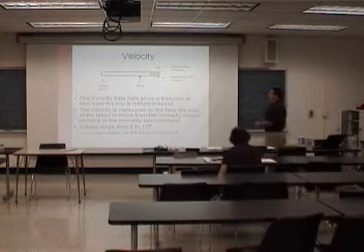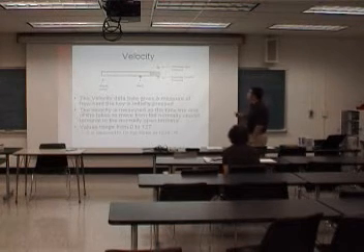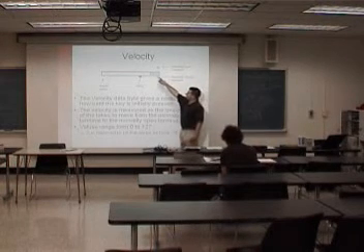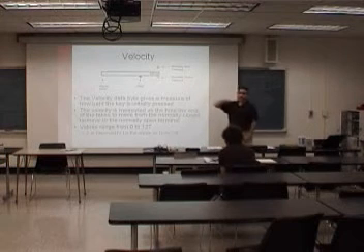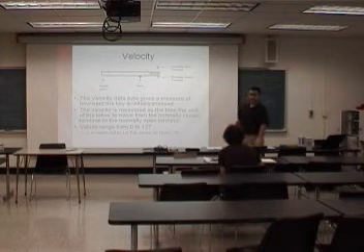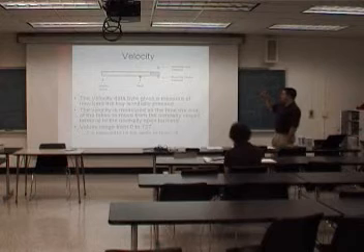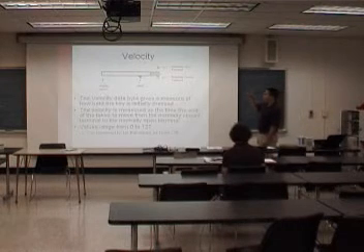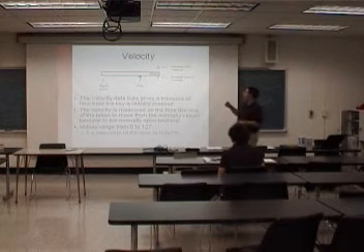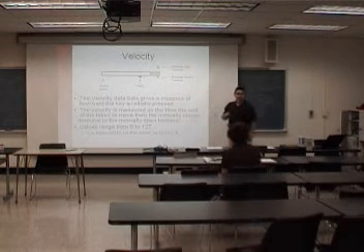Velocity is exactly like you said. It's basically when you push down on the key, you think about having two switch terminals. One that's normally closed, that's in contact with the back side of the key when the key is not pressed, and then one that is normally open that's only contacted when the key is depressed. So velocity is quite literally the amount of time it takes for it to go from normally closed to normally open. So a low velocity number means it took a long amount of time to traverse this distance. And a fast one means it was hit quickly.